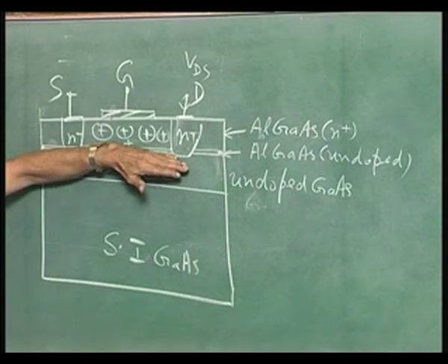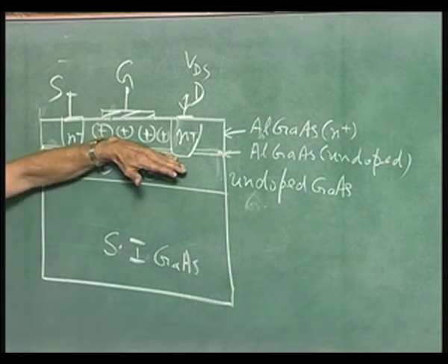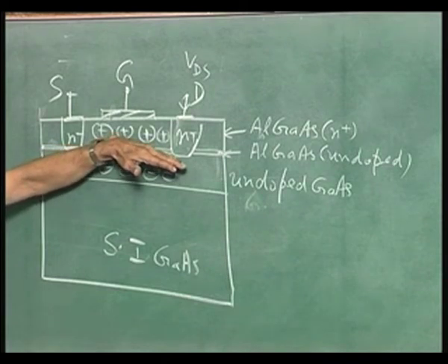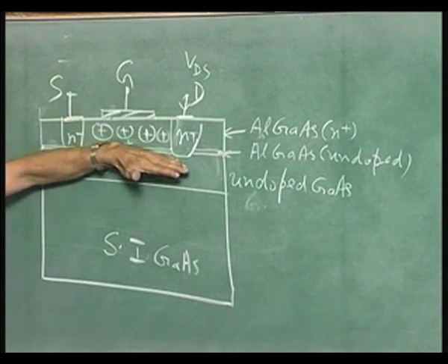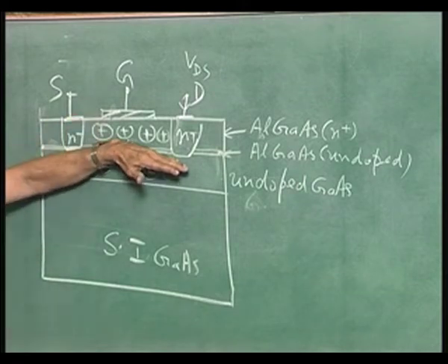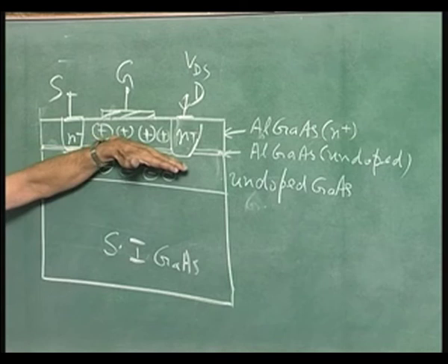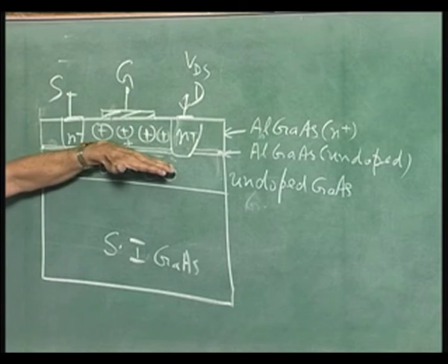Now, in the MOSFET, you can deplete the channel completely by the built-in potential itself, or apply a negative voltage to the gate, so that the entire channel is depleted. What is the voltage required to apply to the gate, so that this channel is fully depleted? That is the threshold voltage of the MOSFET, that is VBI minus VP0. VBI of the Schottky barrier, not of this junction, minus the pinch off voltage gives you the voltage that we have supplied to the gate to pinch off completely.